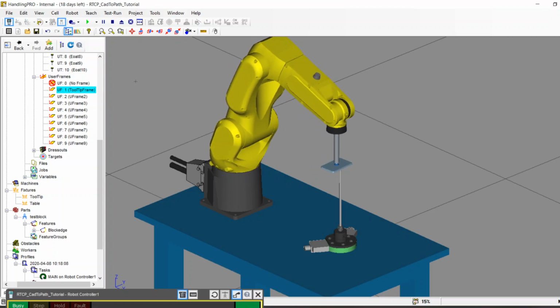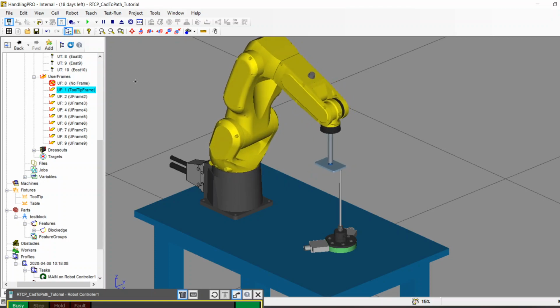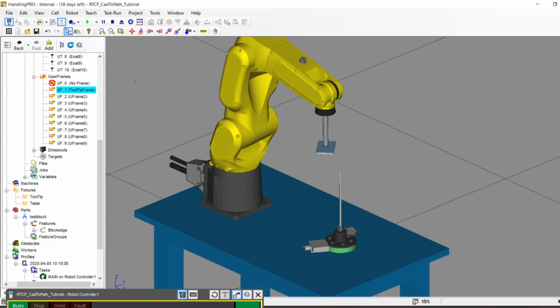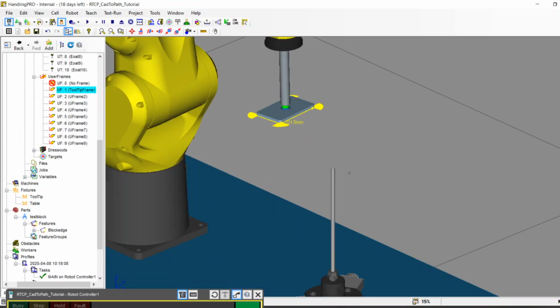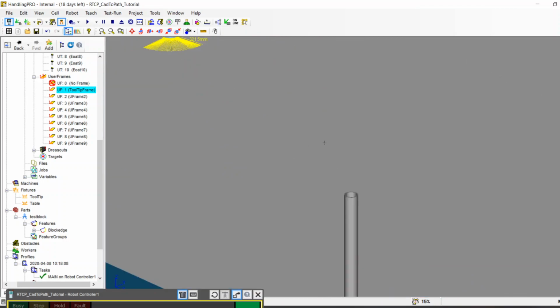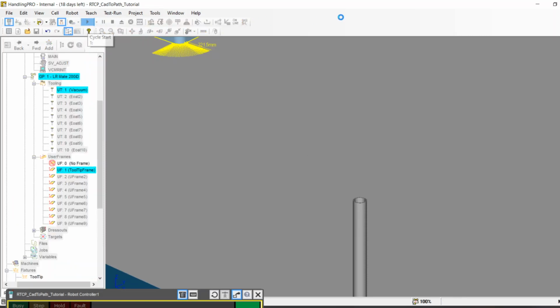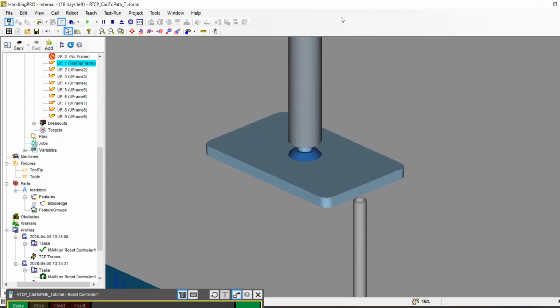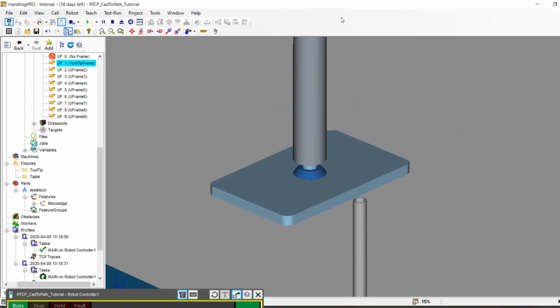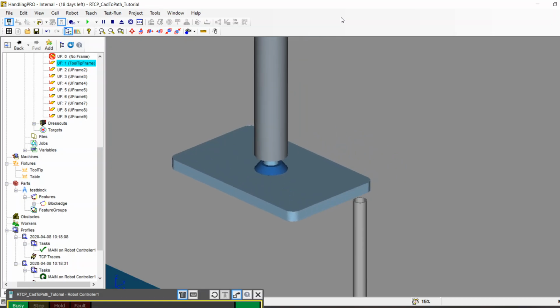Go. So that robot is tracing that line right across that tool center point, unwinds itself, goes back home. Let's zoom in on that and watch it again. Little close-up action. Pay attention to that point of contact. Run. And you can see how the edge of that part never leaves the RTCP, that zero point of the frame.